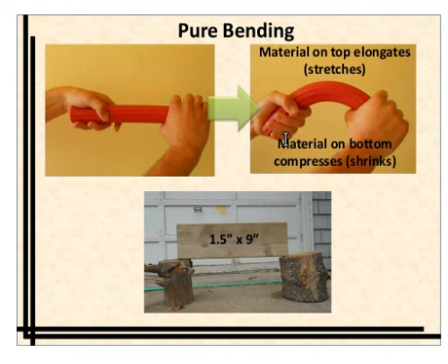And if you look at the bottom part of the beam, all this material has been smashed together, so we'd say that's in compression. All this material had to shrink to assume this shape. So what we say is all the material down here is in compression, and all the material on the upper half of the beam is in tension.